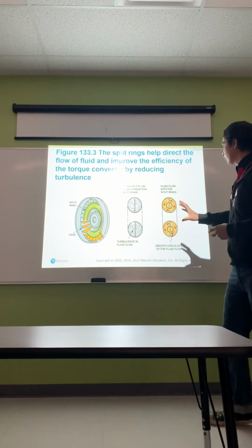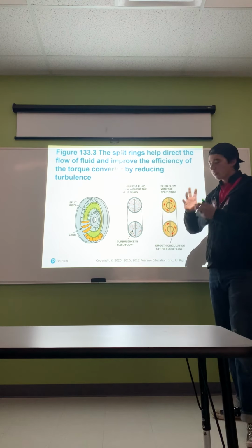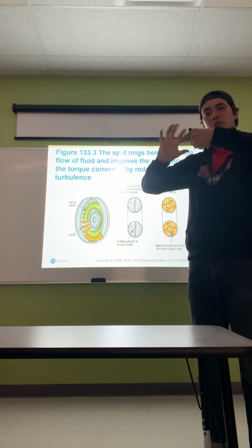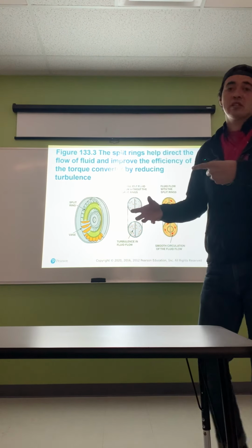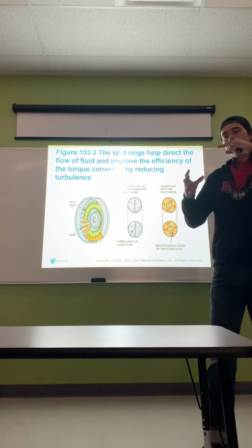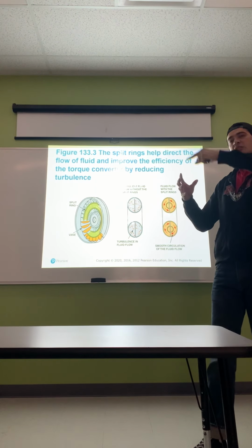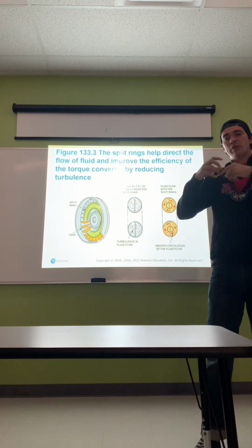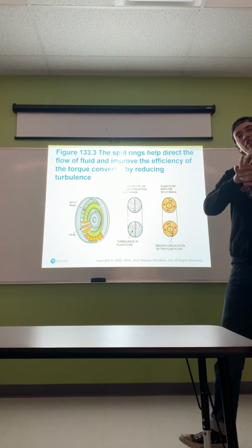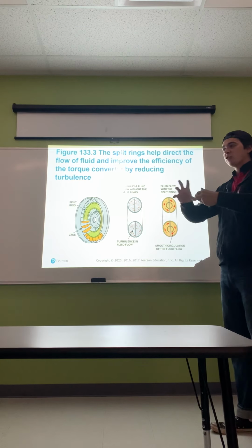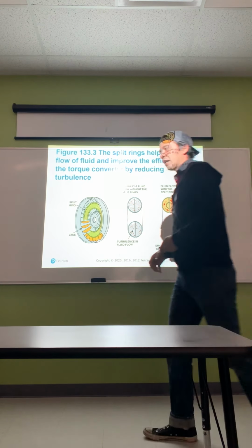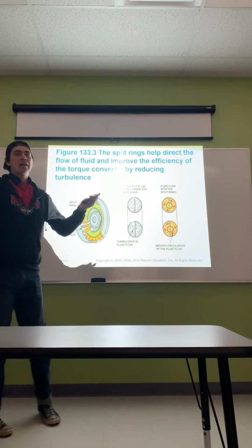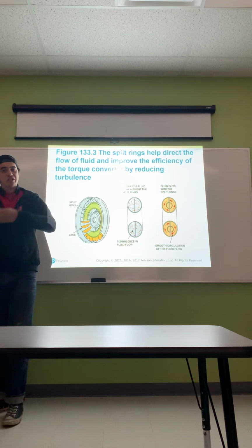As the torque converter rotates, there are two sections that are separate. One's spinning with the engine, the other's spinning with the transmission, or not spinning, depending on if you're stationary. As the portion attached to the engine rotates, fluid is pushed through inside. It's basically creating pressure. That pressure is transferred through the fluid, which then gets transferred to the transmission. Think of it like a clutch that turns on and off automatically depending on RPM and how much load is being put into the transmission.